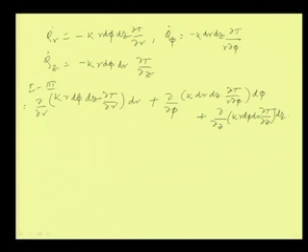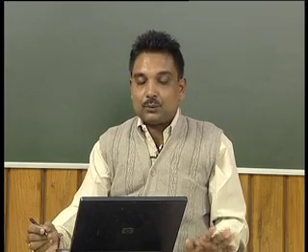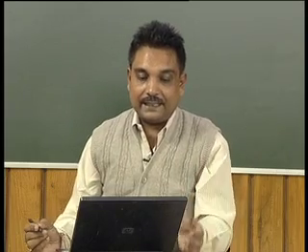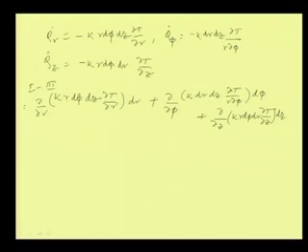Now, again we will assume that k is independent of the coordinates. So, under that situation we can take the k out, but because r is there, r cannot be taken out. So, this is equal to k d phi dz into dr into del by del r of r del T by del r.